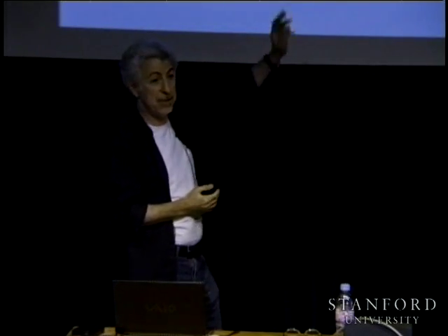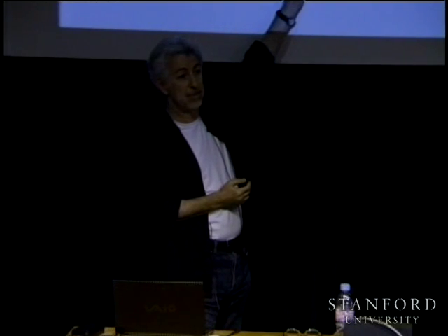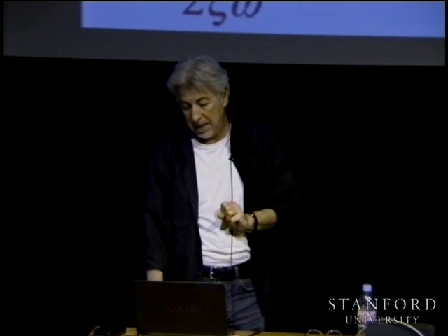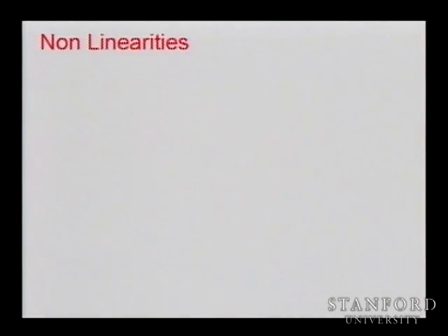Okay, so in this case, what is omega for this system? It is simply the square root of kp prime. And okay, now we are going to introduce one more element. We talked about it on Monday, and this is just a tiny nonlinearity. Let's add some friction. So we started with the system without any nonlinearity, and now I'm just adding a little bit of friction, nonlinear friction, like some stiction on that joint.